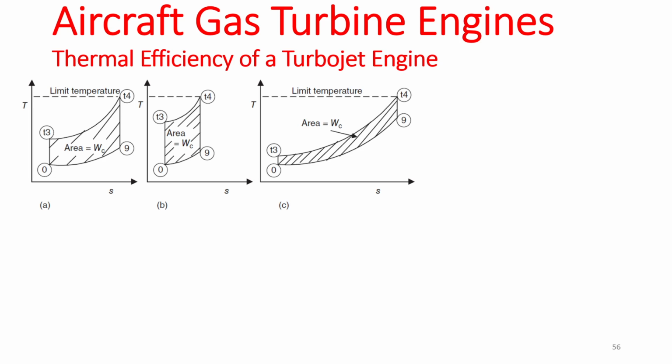Okay. So let's go back to the discussion we had at the beginning. The idea was you want to have an optimum pressure ratio that will give you a specific thermal efficiency. Okay? So you cannot have both a maximum efficiency and a maximum thrust, right? That's not going to happen. There is always a compromise between the two. So you have to make a compromise, right? You have to find an optimal solution.